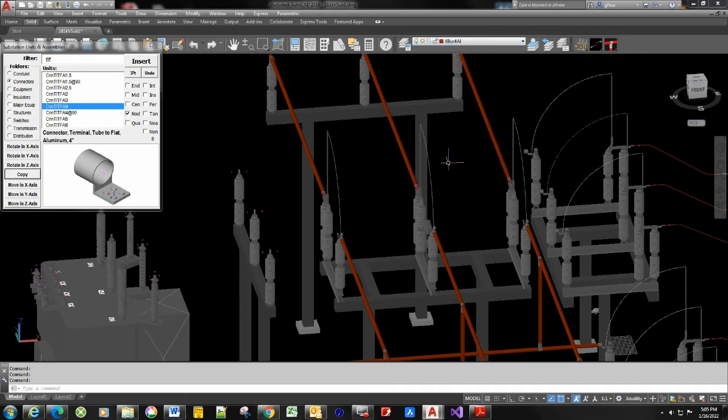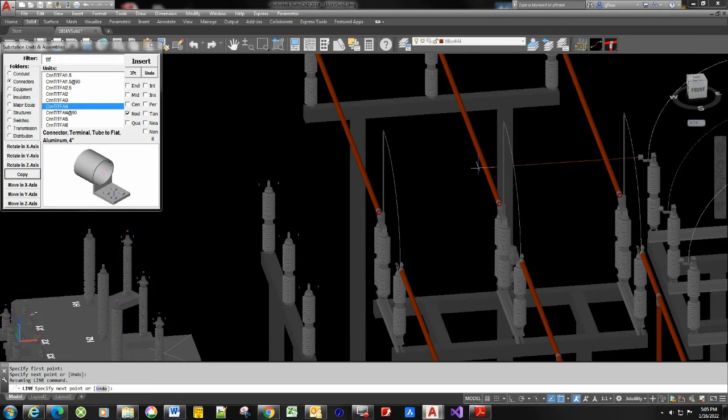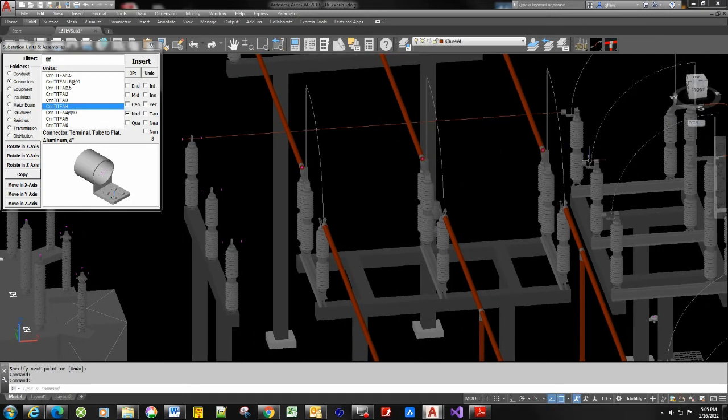And so we're going to put in a line, and here will be the first time I've actually, I think, used an AutoCAD command by typing it in or selecting it from a menu or any such. So we're just going to say line, and there's a node on the back side of this connector, and we're going to take it to this node on the far side of this connector, and then hit enter to terminate that. And here we can just draw that line 2 more times. However, we can use a copy on that line, and it will copy that line from the start end of the line. And so we can easily copy that 2 more times, and now we've got our lines here.